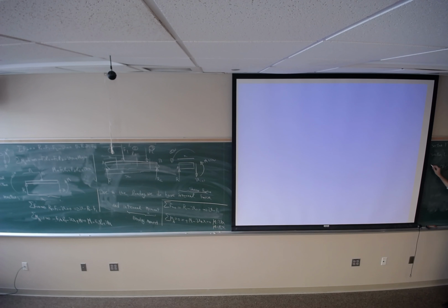These are shear force for section 1, section 2, and section 3, which covers entire of the beam, and these are the moment or bending moment for entire of the beam. So if you plot this graph, x-axis is representing the location of the beam. It's going to start from 0 up to L, which is the length of the beam. And here, the y-axis is representing the shear force.